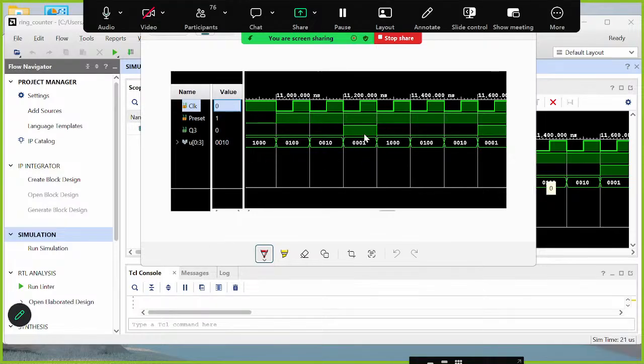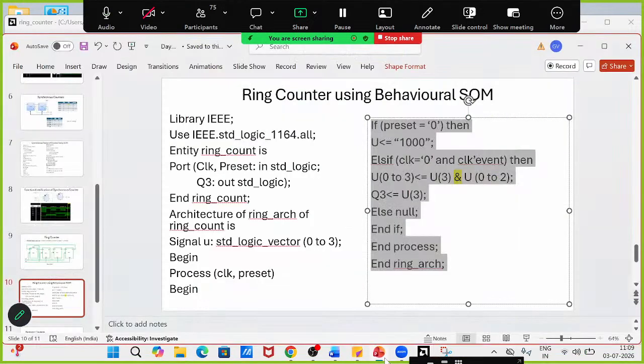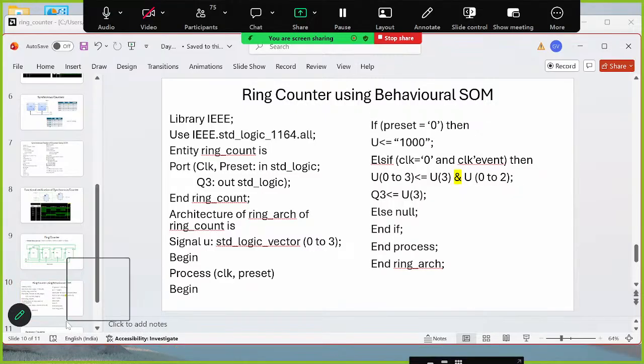Your logic depends upon the hardware circuitry that you have generated. So if your logic is not correct, and you have generated the hardware and downloaded that program into the FPGA, then at the hardware also you are not getting the correct output for some of the inputs. So this must be checked and verified fully in all aspects before jumping directly onto the next level. Okay, hope you got my point.